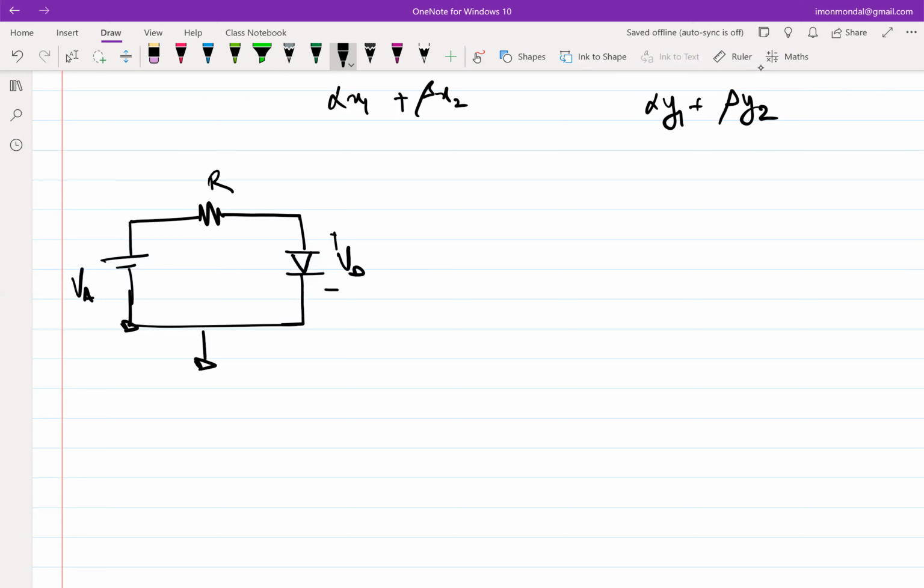So again, before proceeding, just to ensure that we are on the same page, in order to analyze this circuit, we require the help of KVL, KCL, and what else? Diode characteristics. So essentially, to analyze any circuits, you need three things. One is obviously the good old Kirchhoff's laws, and the third thing is the current voltage relationship, or the IV relationship, of all the elements in the network. Given these three things, in principle, we should be able to analyze any circuit.